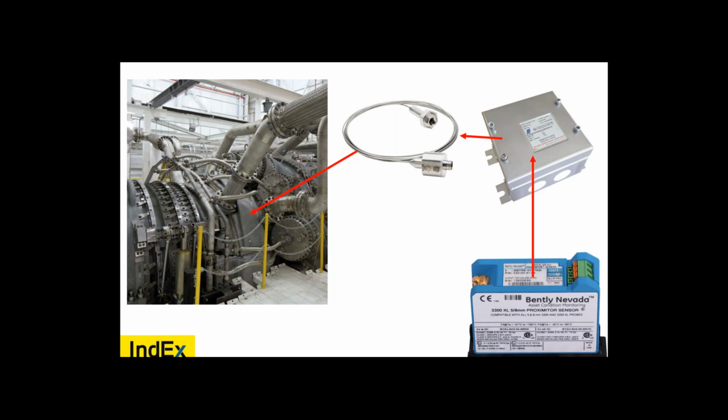EX eC, all of your internal components would have to be EX eC. So all your terminals could no longer be EX nA. So that transition period from one edition to another causes many problems for manufacturers. Okay? Is it mandatory that all internal components need to be EX certified? For EX e and nA, yes.